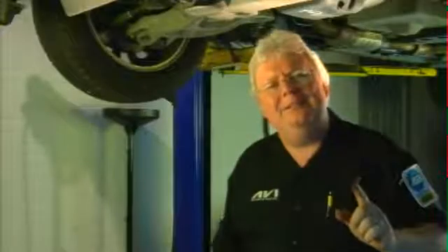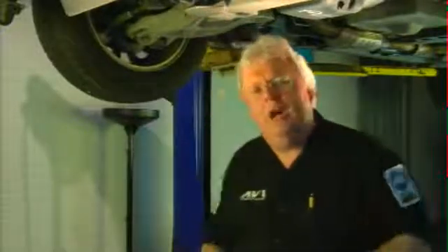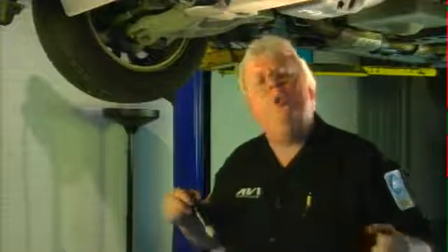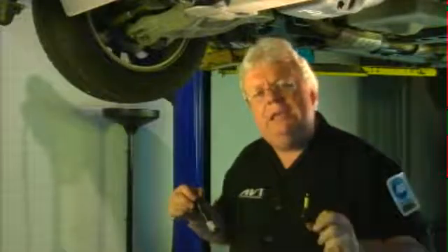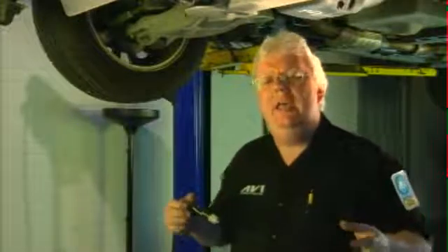And that's the kind of system that has a solenoid that is pulse width modulated to control the flow of high pressure power steering fluid into the rack to get you a little stiffer steering when you're moving down the road at speed when you don't really need power steering, and then give you a very well power assisted steering for effortless parking at slow speeds, when you're parking in a parking lot, something of that nature. So VSS is an input to that sensor.